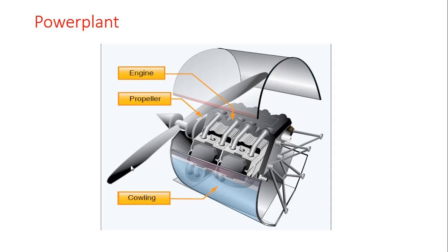Engines may be turned around to be pushers with the propeller at the rear. There are significant factors involved in the design of a propeller that impact its effectiveness. One is the angle of the propeller blade, which is measured against the hub of the propeller, keeps the angle of attack relatively constant along the span of the propeller blade, reducing or eliminating the possibility of a stall.